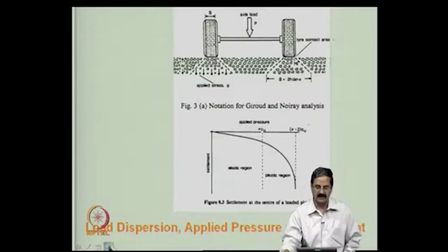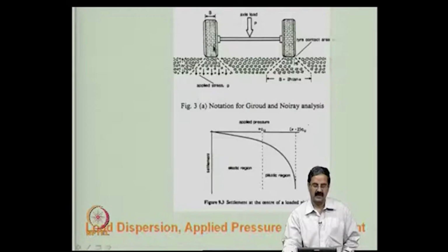And how is the load acting here? Say suppose I put a reinforcement, how does it work? Actually, what I am doing is, you apply a standard axle load here, B is the dimension, and L is in the opposite direction, perpendicular to that, and we assume some dispersion angle, right.